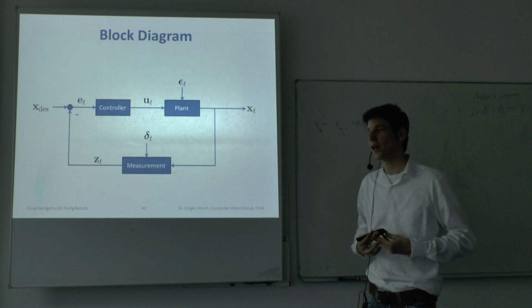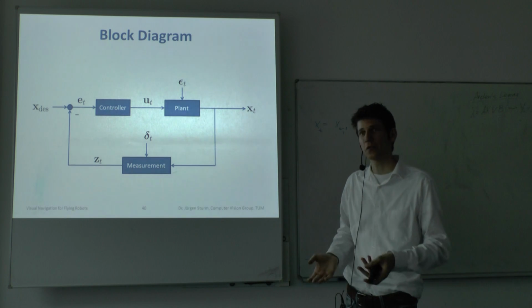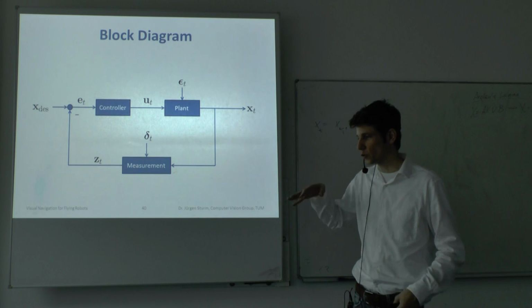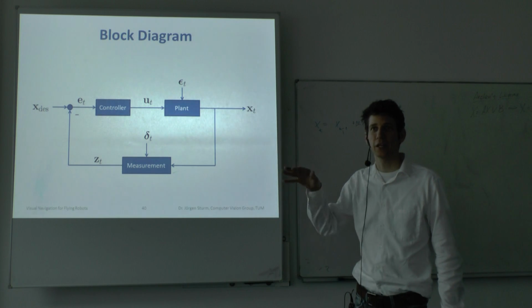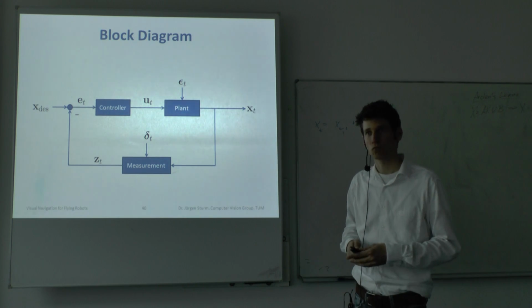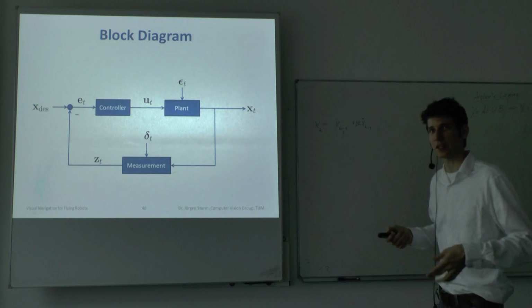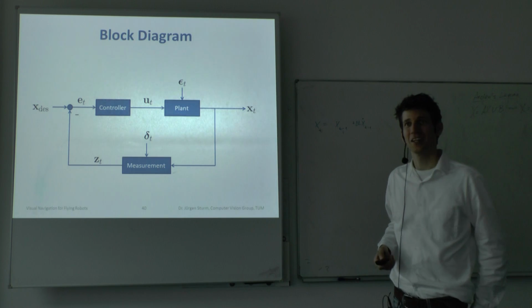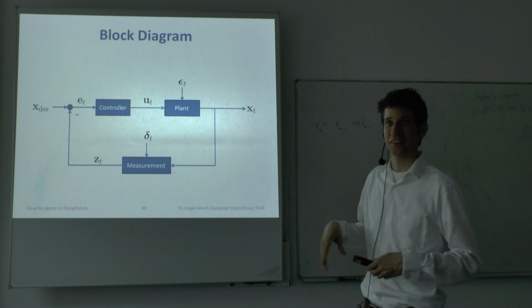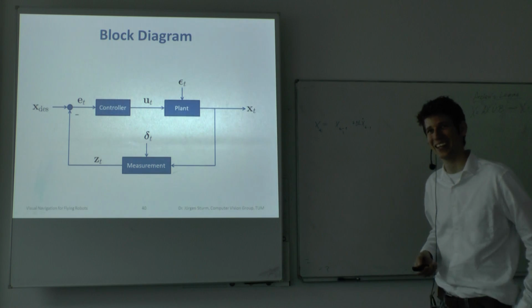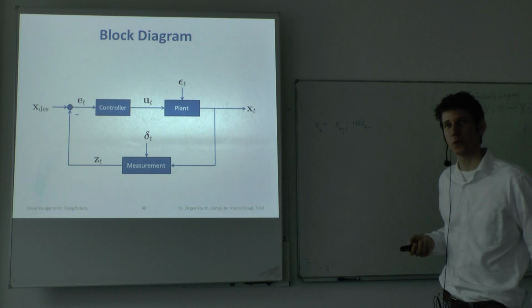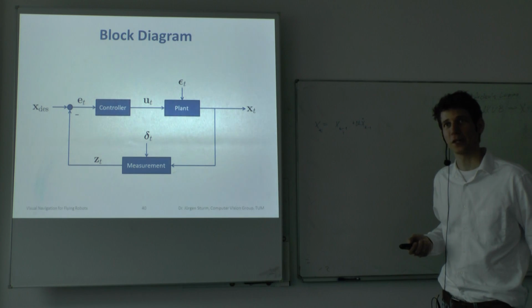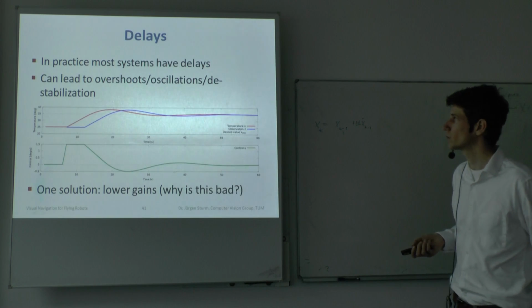So with the Ardrone, for example, you could say the ultrasound sensor has a certain noise. So you could do several measurements at different heights and then see how much they change. But it's a problem in itself to estimate the noise. Most of the time, people just guess, to be honest. But if you want to do it more elaborately, more sophisticated, then you would have to run real experiments and find out the shape of this noise.